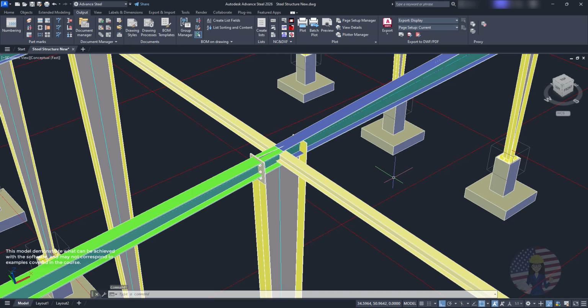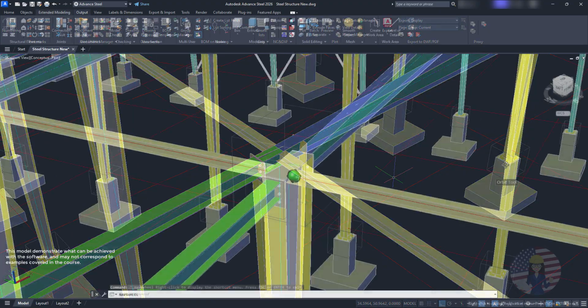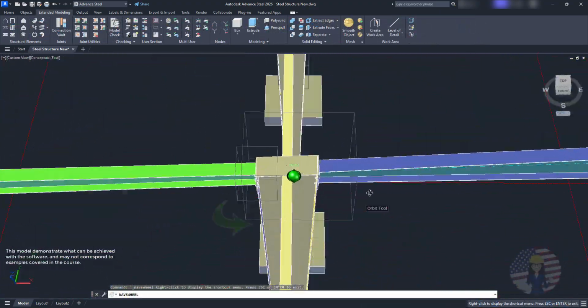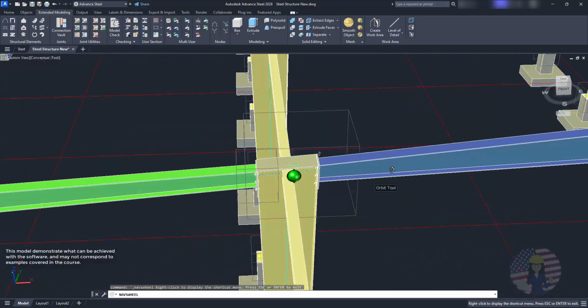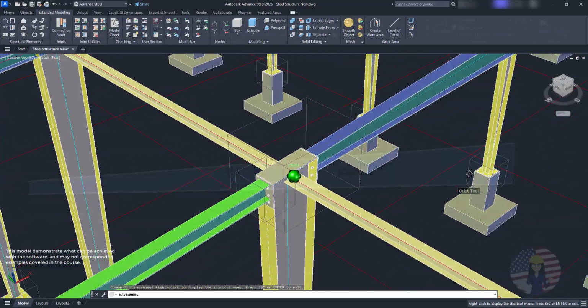So these types of non-prismatic members are actually quite common in steel frame construction, as they provide a lighter and more efficient solution when covering large spans, as one will have full control over the geometry of the section. From the thickness of each plate corresponding to the flanges and web of the member, to their specific geometry along the span, all the way to the type of welding.